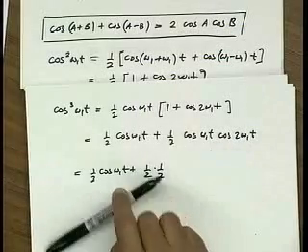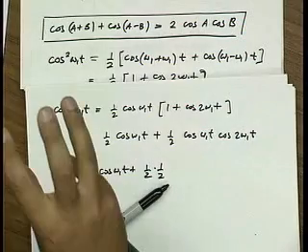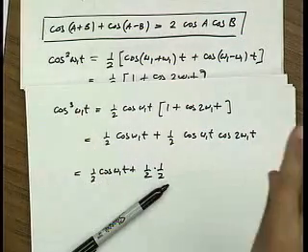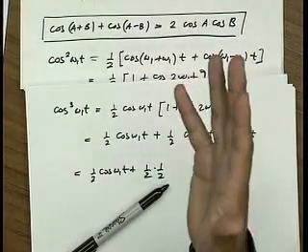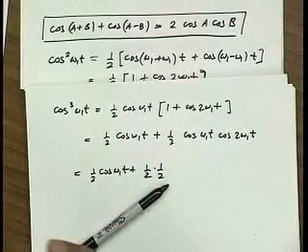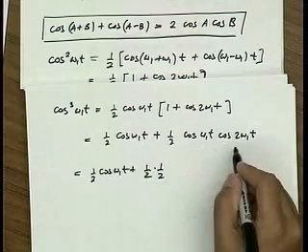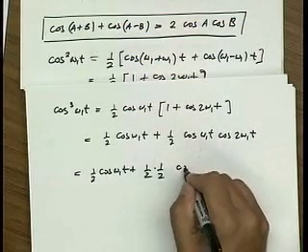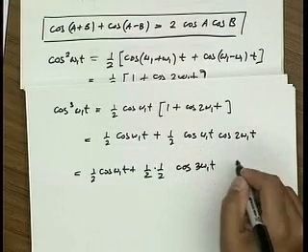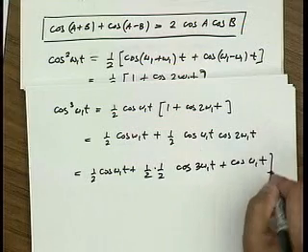So the important point to take away is when you multiply two cosines, you get a sum cosine and you get a difference cosine, right? And basically it looks like one cosine is modulating the other cosine. So the sum frequency here is cosine 3 omega 1t, and the difference frequency is cosine omega 1t.